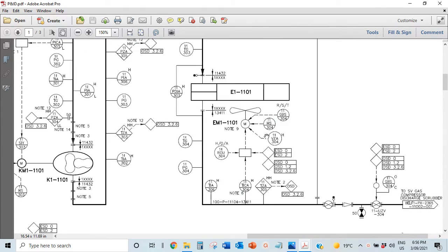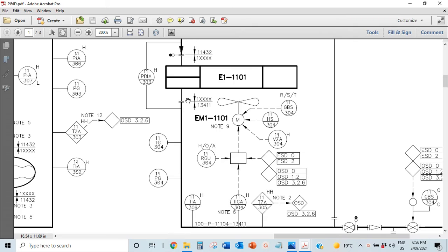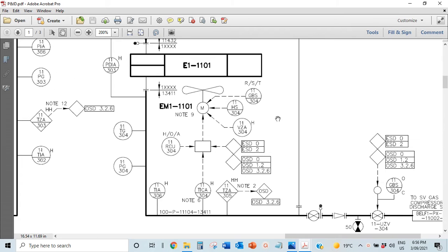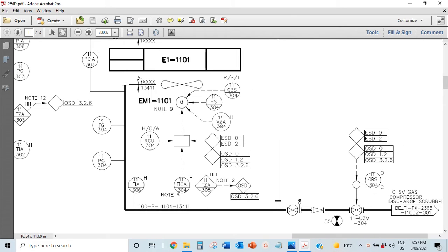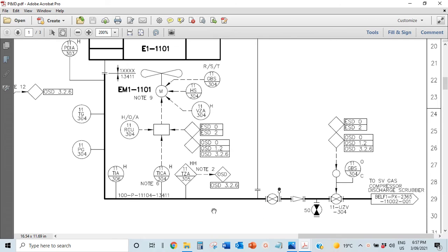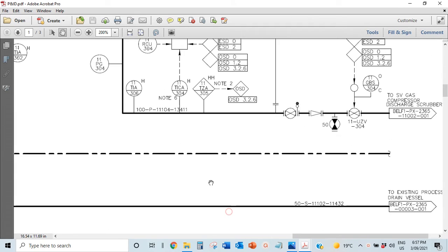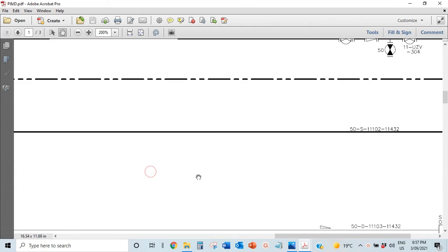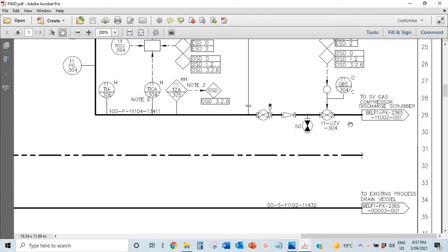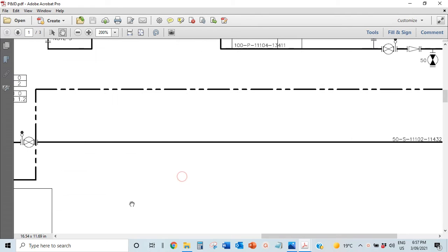But the other problem is when this temperature drops a lot, it's kind of what they call the Joule-Thomson effect. When the pressure drops very much, you're going to produce some liquid. It's just normal. Anywhere you really drop the pressure of a gas, liquids form. It's condensation. It's normal physics. So when that happens, automatically you now have liquids in your stream with the gas.